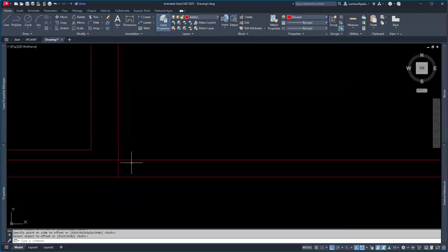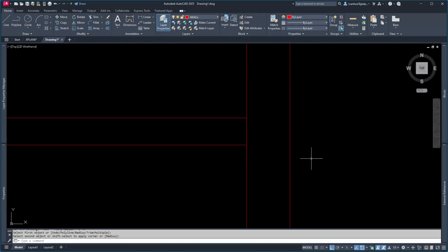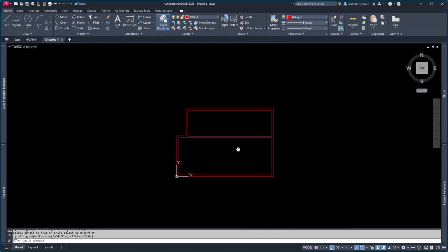And then I'll just come in here and I'll fillet it. It's already at 0. Take care of that. Come over to the other side and just trim this out. And enter, tap the space bar. There we go. And then make sure you're saving and saving often. So Control S. Also, this UCS icon, a little refresher here. I don't want it there. When I made my HWC template, I never moved it. So I have to do that now. So I'm going to type in UCS origin.